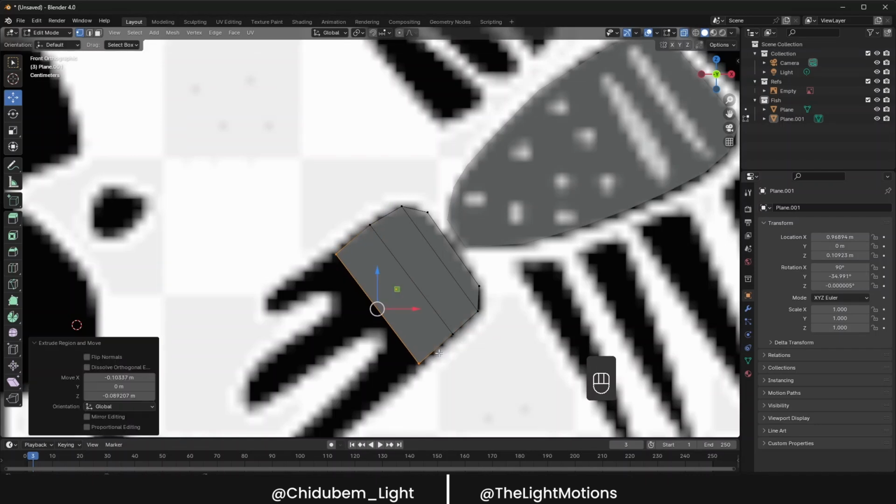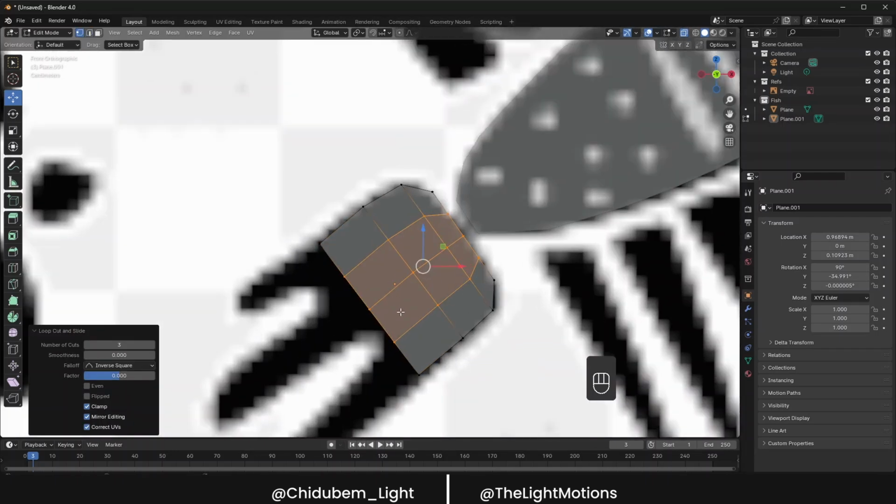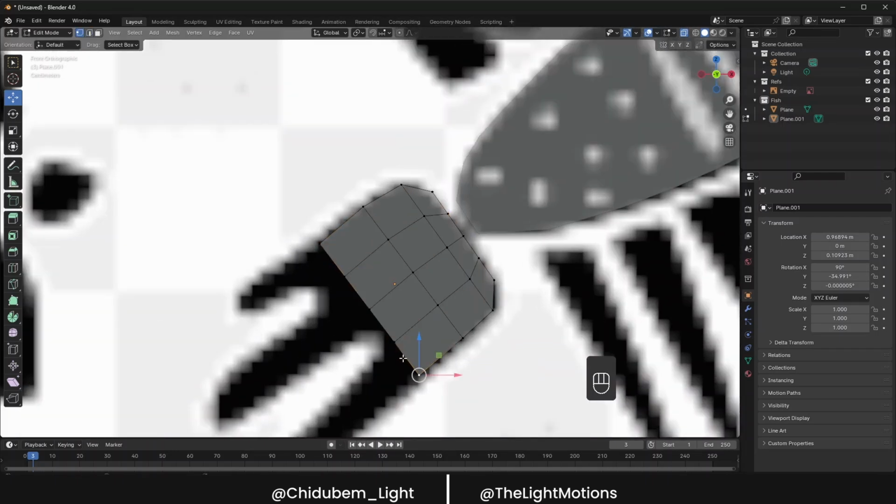So we have three of these coming here. You can find this face here, there's another face here, there's another face here, right? So that means we need a loop cut. To bring down the loop cut, Control R and give it another one, because we need three. Click to establish. So that means we can just have this selected, that one and this one, both of them selected that way.